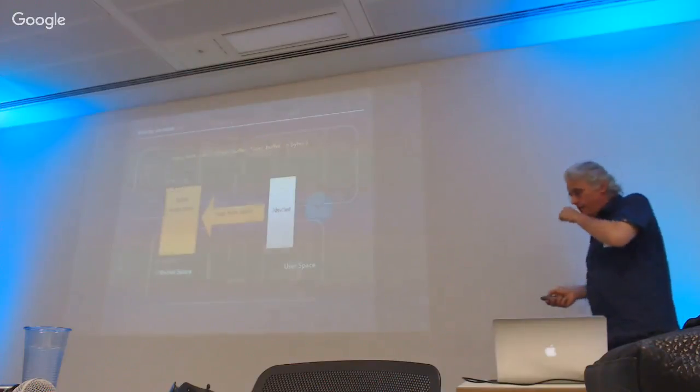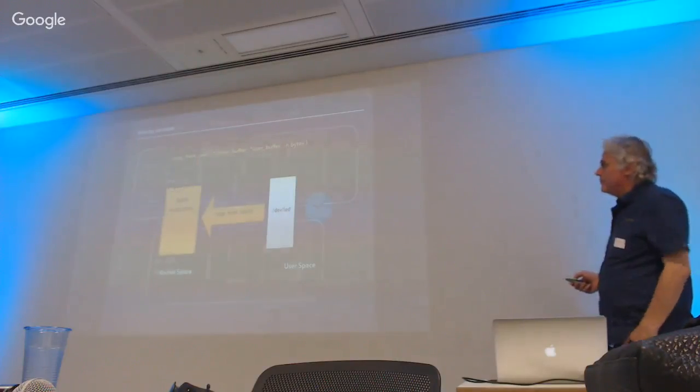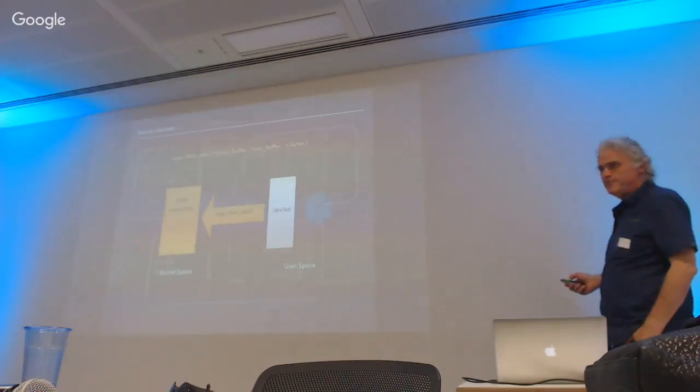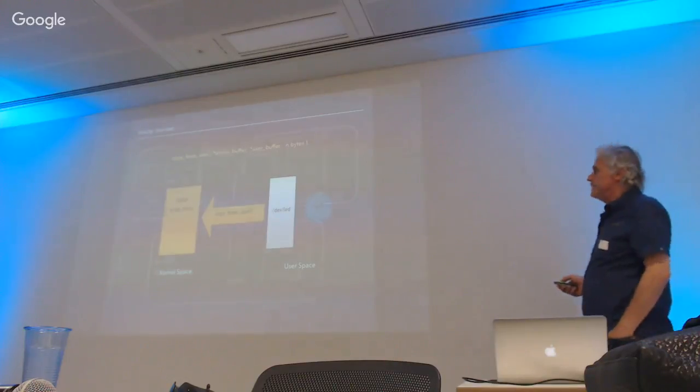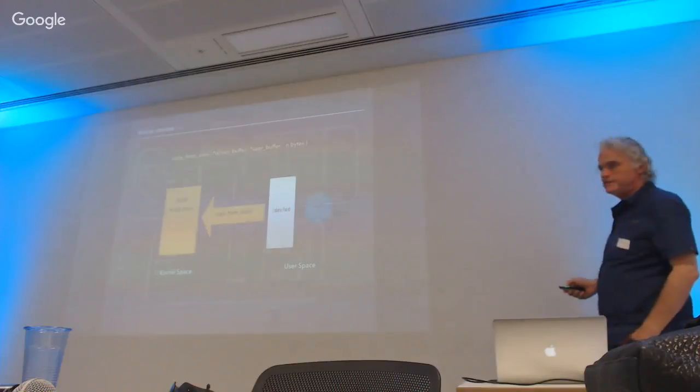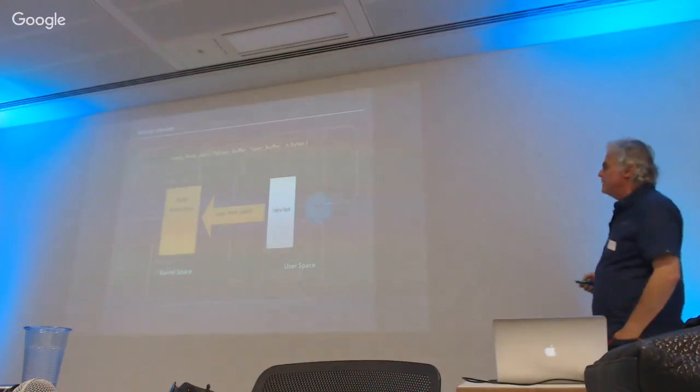So in the driver code, we have a special function called copy_from_user. And what we need to do is set up a buffer in the kernel space, so in our kernel driver. I'll show you in a minute, we'll set up a buffer also in the application code.